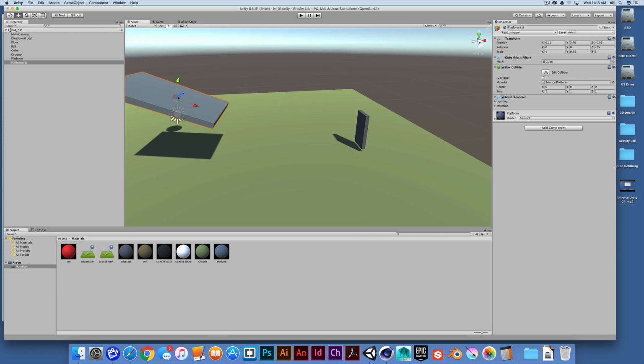So in other words, if I click and drag on the blue axis, no matter how sloppy my mouse is, it's not going to move in Z or in foreground background space. Okay, so you can see as I drag this around, it's staying in line. Okay, if I grab it by the red axis, it only slides in the direction of the axis or the Y. And what I'm doing is I'm selecting the blue, restricting it according to the blue axis or the Z axis, allowing me to move it in Y or X at the same time.